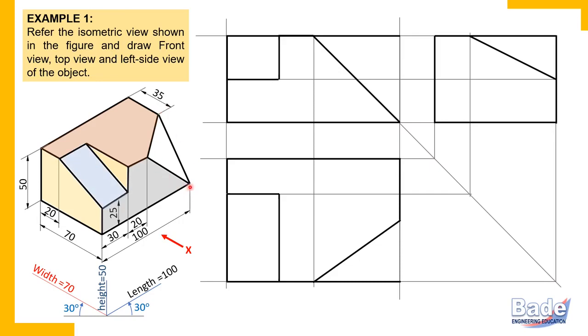Now, we have done this exercise in the last video. This corner is the right side bottom corner and on the front. Now in top view, let's identify this corner. It is at the bottom, which has no significance at least for top view, because in top view, top and bottom you cannot separate. But it is on the right side. This corner is on the right end. So on the right end and on the front, that is this corner.